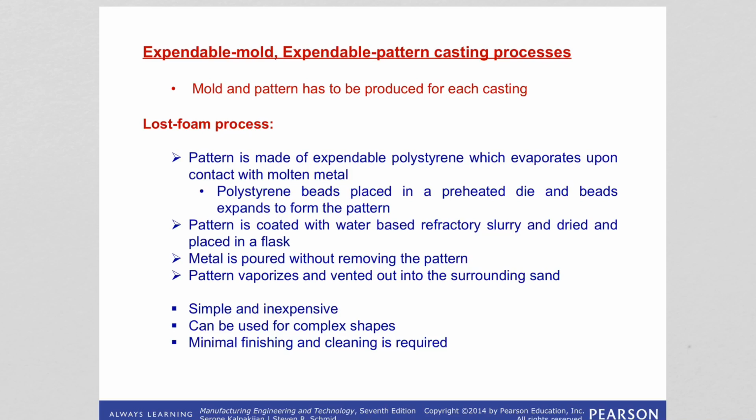This technique is using a polystyrene pattern, which evaporates upon contact with the molten metal to form the cavity. This technique has become an important technique to cast ferrous and non-ferrous metals.